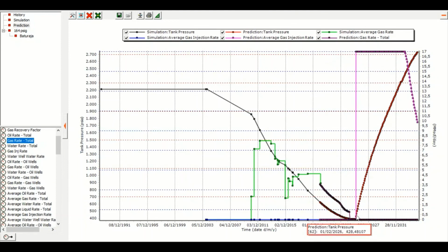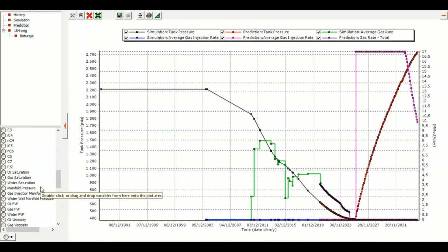The reservoir pressure continues to increase. Yeah. And then because the difference between reservoir pressure and flowing bottom hole injection pressure continues to decrease, of course, the injectivity will drop and the injection rate will decrease.